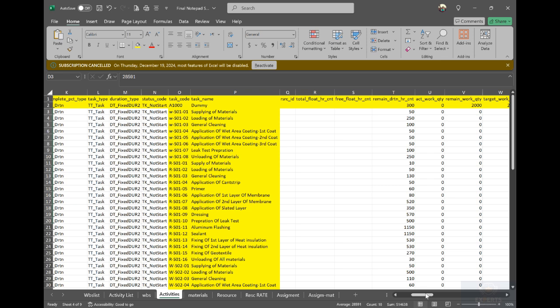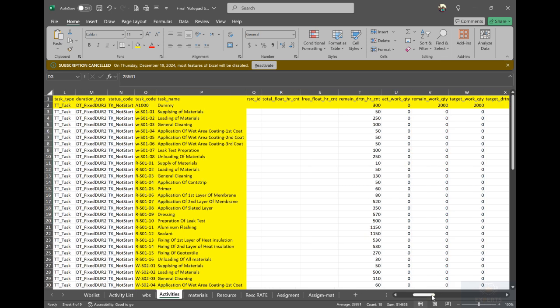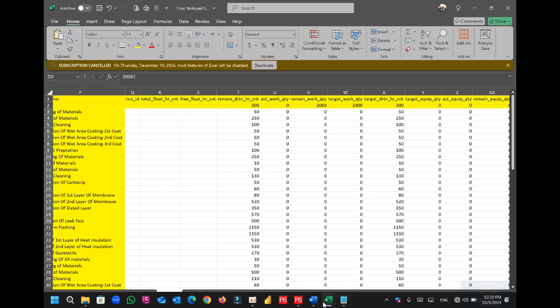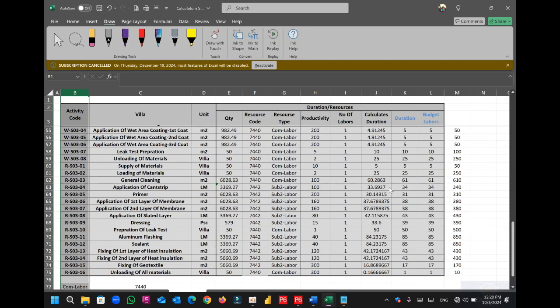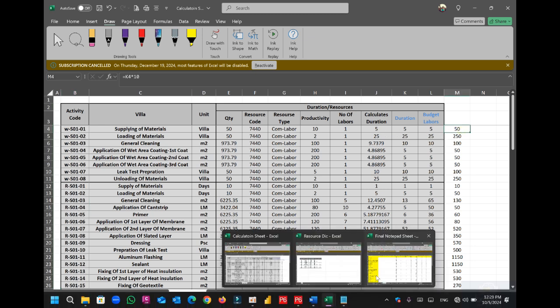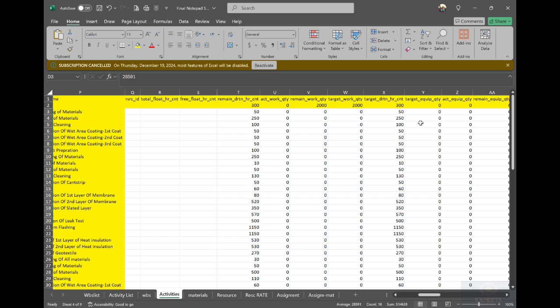We will go to this column, remaining durations, which is the remaining or the budgeting. Target is equal to budget. So we will check the durations from our sheets. Here I copy this one, equal multiply by 10, multiply the duration because it's by hours. So I will insert all this here. And it will also equal the budget, because in baseline creation the budget is equal to remaining, since there is no actual up to now.